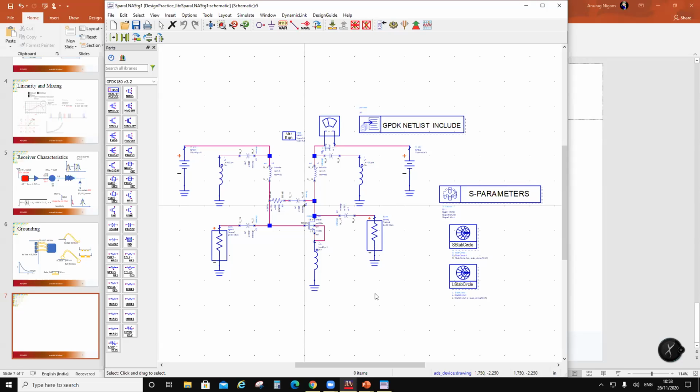How? The topology won't allow you. And this guy was struggling for 6 months trying to get 30 dB isolation on a Gilbert cell using resistors. The best he could get was 9 dB. When I went there, I said you are struggling for a useless reason. It's not possible, right? So stick to the theory if you are a fresher,